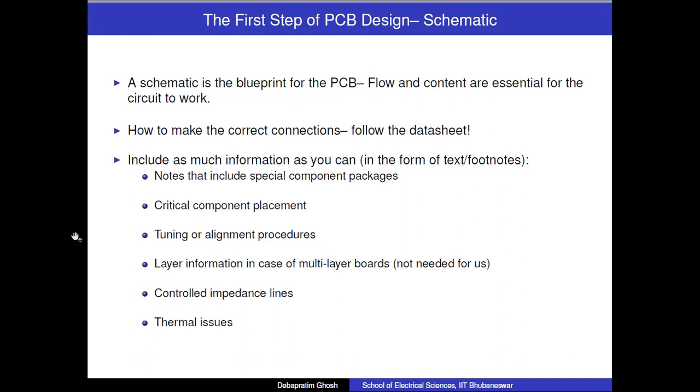It looks just like any circuit simulator where you have components and their interconnections. Now obviously how to make the correct connections you will know. You must have read the datasheet of the different parts before you make the schematic. Now try to include as much information as you can in the schematic, because later on if there is somebody else who is using the schematic for their own purpose, they may not be immediately familiar with what you are trying to do. So these notes will be very critical or useful in helping them.